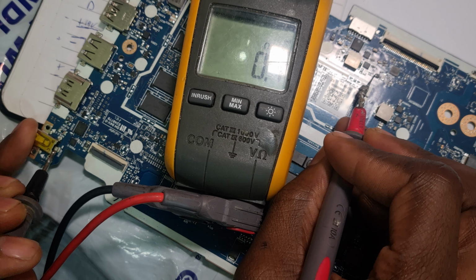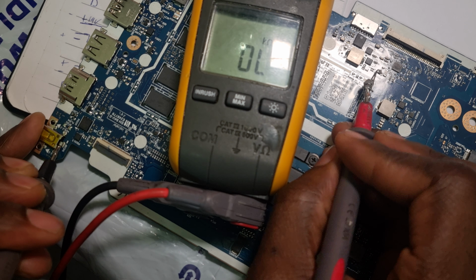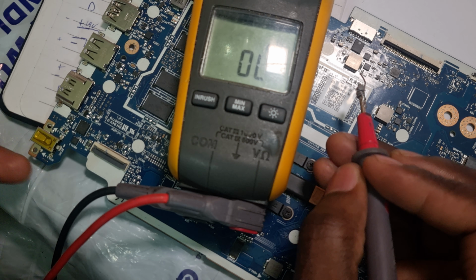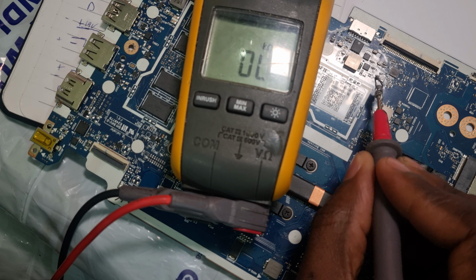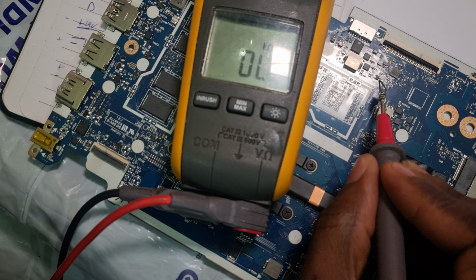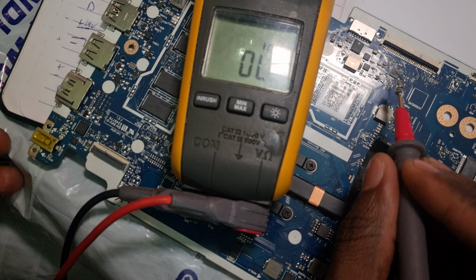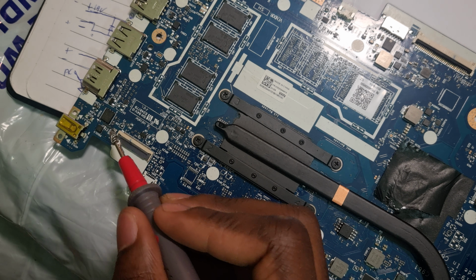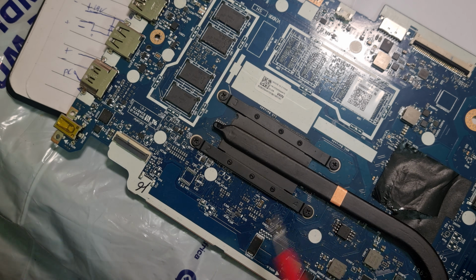So if you've got a connection coming from the charging port, the moment you plug a charger here by the DC inject, that 19 volts goes straight into this diode here, it gives us an output through that resistor into the PQIC, which is the one that then sends a signal to these first 2 MOSFETs, a 24 volts signal to enable these 2 MOSFETs so that they can allow now power to get into the main power rail.